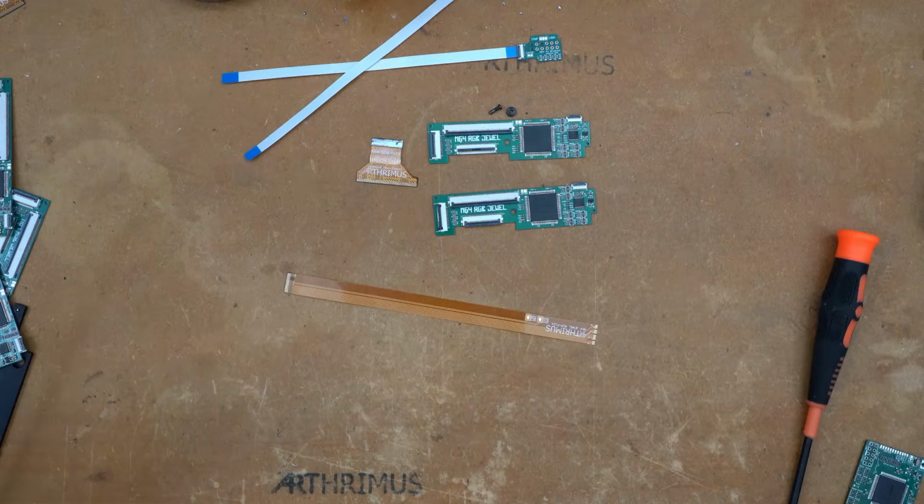He created a universal N64 RGB mod that worked for all N64 models, whether they had the RGB DAC inside of them or not, which was kind of groundbreaking for N64, because it used to be that only the earliest revision N64s could actually be RGB modded, because the early models had an RGB DAC, but the later models removed the RGB portion of the DAC.